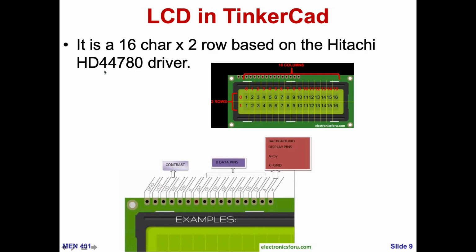The LCD in the Tinkercad is a 16-character, 2-row display, and it is based on the Hitachi HD44780 driver. It has a 16 pins output, as we see them here, and I will now explain the pin out of each one of these pins, also based on the HD44780.